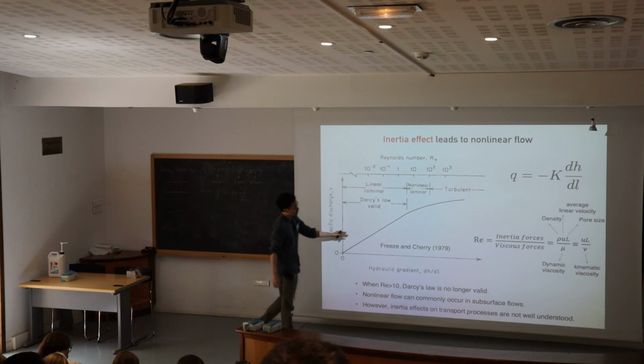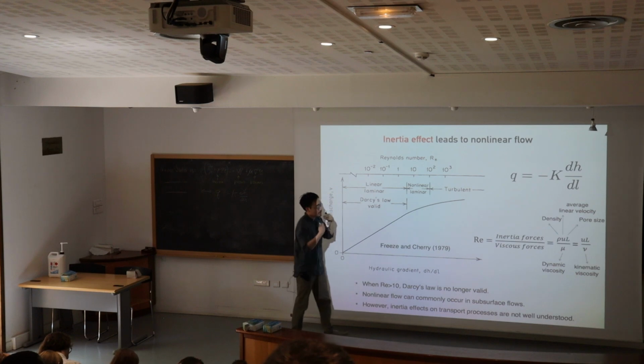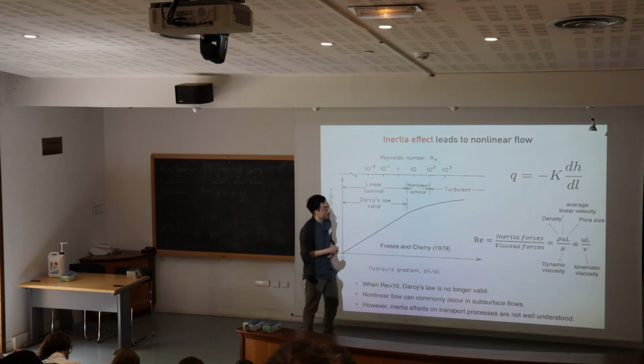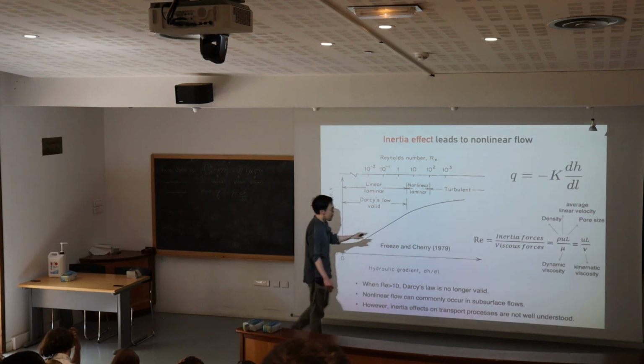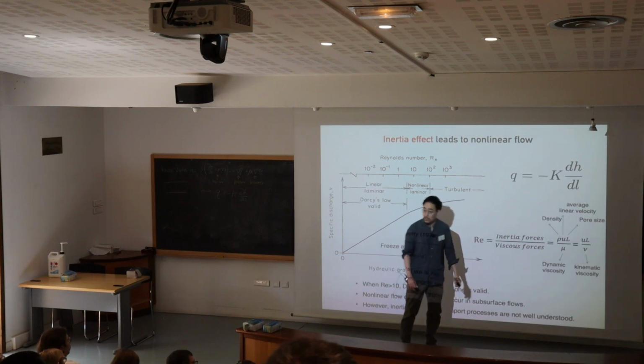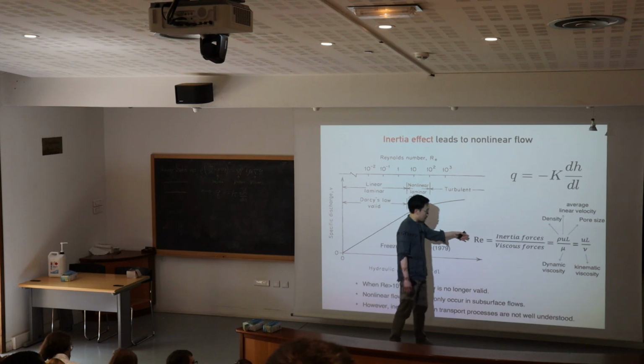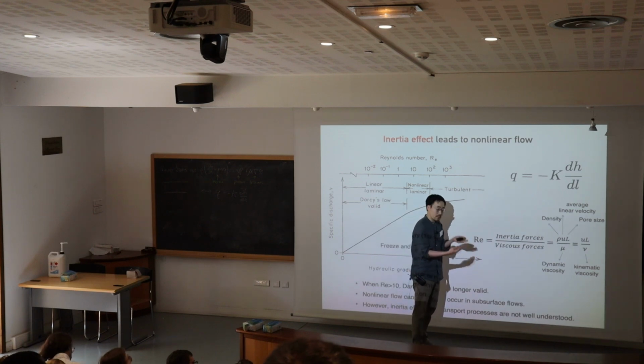Okay, so that's why we are seeing this decay in the hydraulic conductivity as the inertia force is contributing to the frictional energy loss. Another key objective of my lecture is to have a better understanding of the dimensionless numbers, right? I'm sure many of you are familiar, but the key concept is basically comparing the two contributors of the system, right?